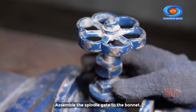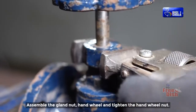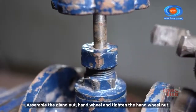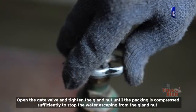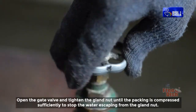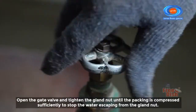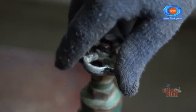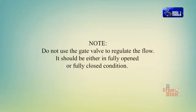Assemble the spindle gate to the bonnet. Assemble the gland nut, hand wheel and tighten the hand wheel nut. Open the gate valve and tighten the gland nut until the packing is compressed sufficiently to stop the water escaping from the gland nut. Note: do not use the gate valve to regulate the flow. It should be either in fully opened or fully closed condition.